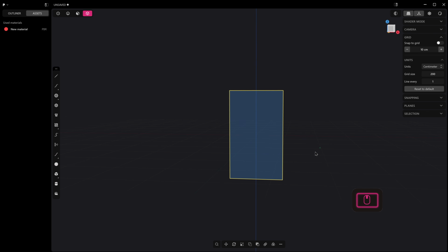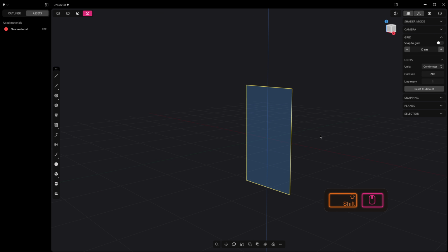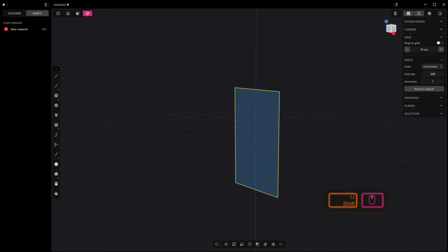And you might think that 30 centimeters tall is a bit tall for a walkie-talkie. So those dimensions may seem a little bit large, but I find that when working in Plasticity, sometimes smaller details have a higher likelihood of an operation failing. So it can be a good practice in some cases to work at double or more the size that you want and then scale everything down later. I just find we run into less problems.